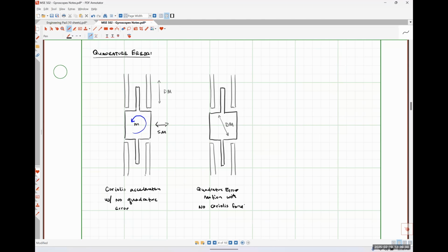So we might do that by applying our normal DC actuation voltage here, and then we might have some small change in our voltage, and we would apply that exact same DC actuation voltage on this leg. And then on the opposite legs, we might do VDC minus some delta V and VDC minus some delta V like so, so that we are essentially attracting, actually, I guess I should have done it plus here and minus on the opposite side for the way that I drew the direction of movement.